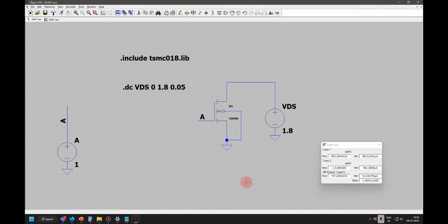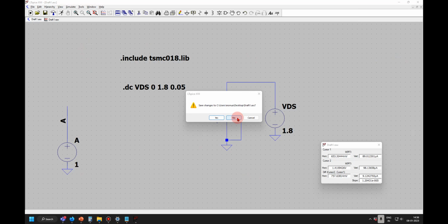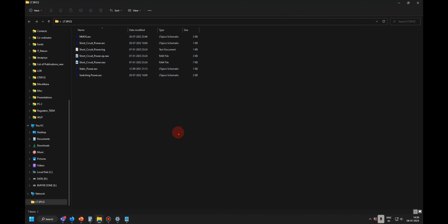Okay. So let me close this. Sir, what is the use of the label? Basically, we are using it for creating complex circuits. I just showed you the full adder, right? If you start drawing wires everywhere, it will become clumsy, and when you are crossing the wires, if an interconnection is made, diagnosing it will be a difficult task. When the system is simulating, it will assume they are connected in the background. Okay.